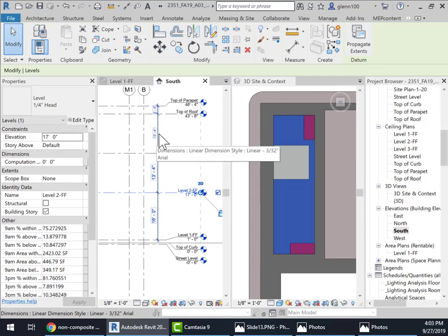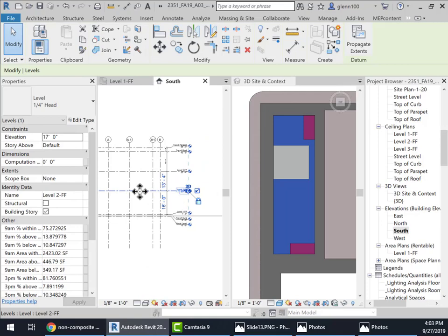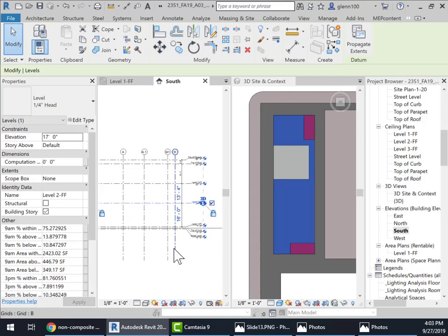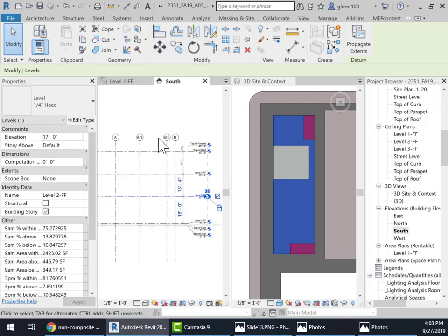And then the next level is the same, 13 foot 4. And then there's the top of the parapet. When we do the parapet, it is 2 foot 8 inches above that. Now those dimensions may change as we work the design and have to make other things fit, but as a general rule, that's the vertical layout. Okay, so that gives you an overview of the project. In the next assignment, we're going to start putting foundations in and raise the frame.